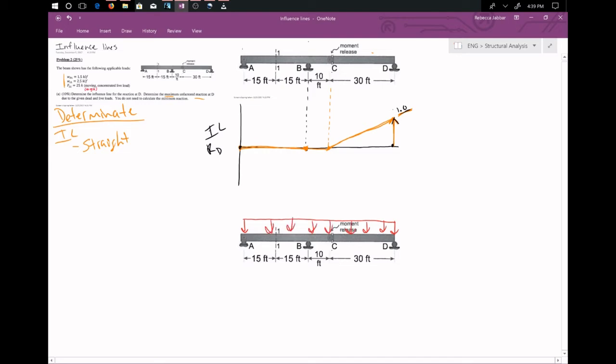So you can see that as going from here to here, and this whole area isn't doing anything. So this will be W sub DL equal to 1.5 kips per linear foot. And then our live load, we're just going to apply it where we have a positive reaction, because it's a live load, it moves, so we have a little more flexibility with it, and adding it over here does nothing for us.